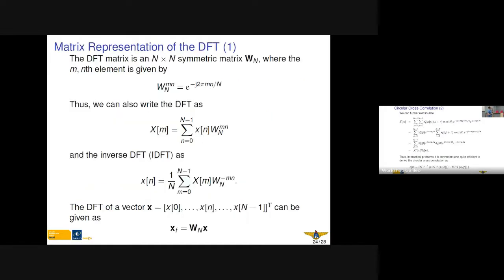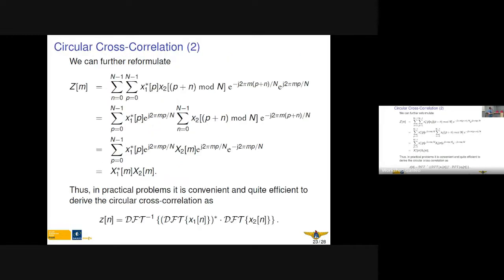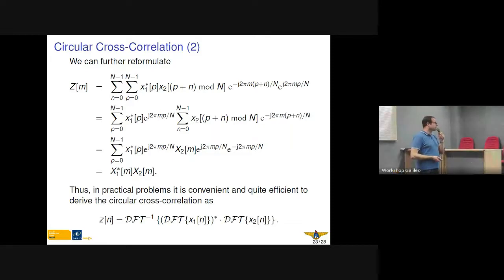What have we achieved with this is that we can calculate the cross correlation function based on the time delays of our received signal and model signal. So we can calculate the cross correlation between the received signal and the model, but only in the resolution of the samples n. But this is coarse enough for us to usually find this maximum that is above the threshold to decide whether the satellite is present or not.